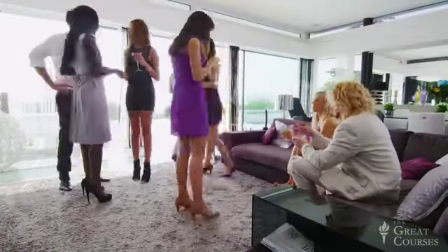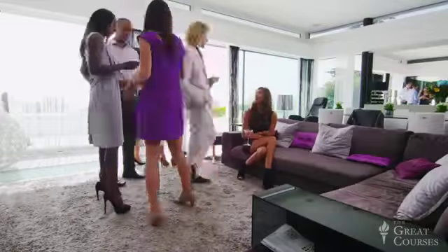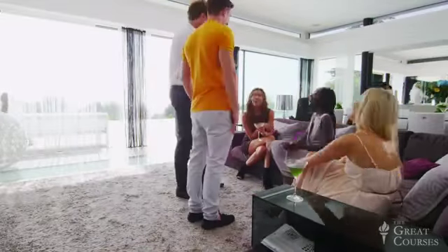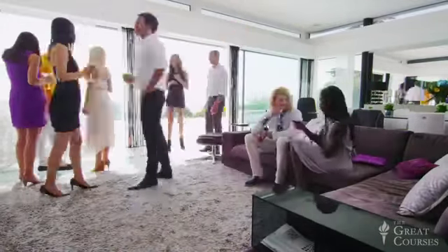Live load consists of the weight of people and all of their movable stuff, like furniture, books, and housewares. Live loads are highly variable in both magnitude and position, and they can change dramatically over time. Given this inherent unpredictability, we need to rely heavily on the institutionalized wisdom of the building code to help us estimate these loads. For example, according to the International Residential Code, my living room floor should be designed to support